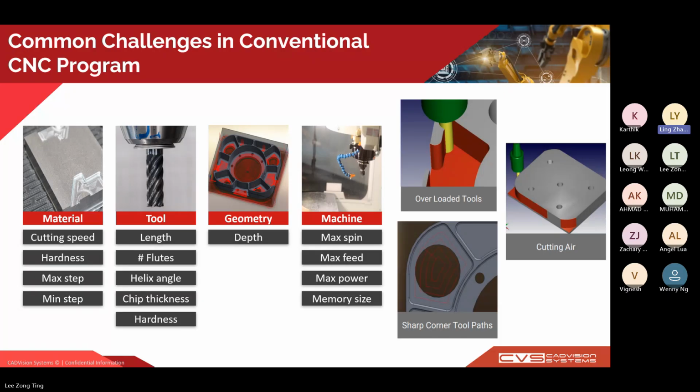Another big limitation of conventional CAM software is its reliance on the fixed step-over toolpath, which, like I mentioned, is the racetrack. This creates consistent tool engagement only in theory, but in practice, especially around sharp corners or very tight curves, the tool will suddenly encounter significantly higher cutting forces because it tends to change angle.